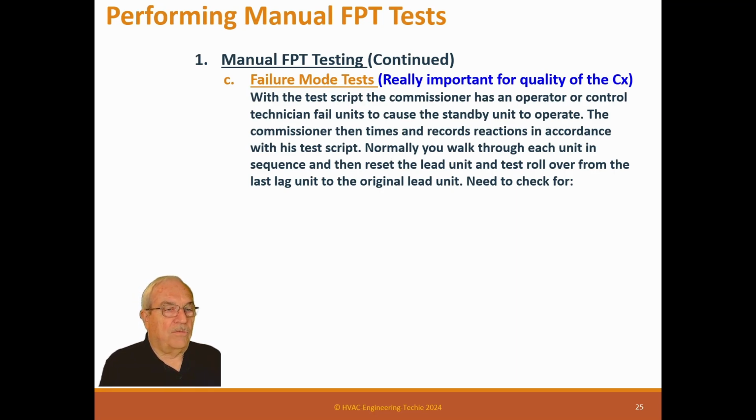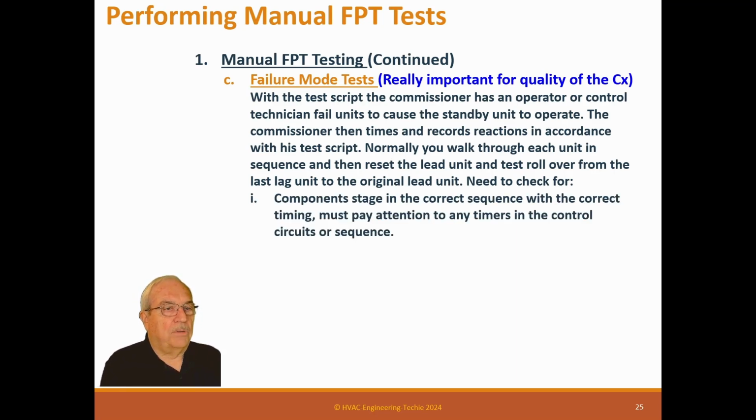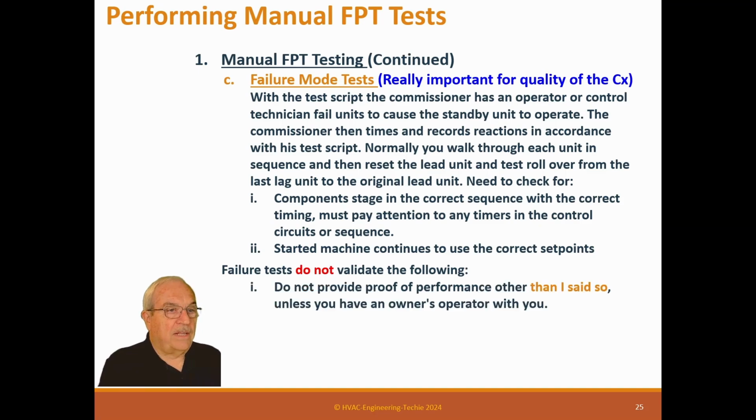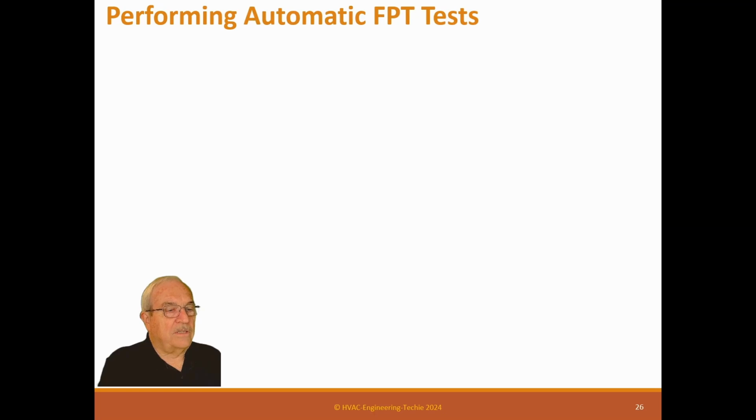Need to check for components staging in the correct sequence with the correct timing. Must pay attention to any timers in the control circuits or sequence. Started machine continues to use the correct set points. Failure tests do not provide proof of performance other than I said so, unless you have an owner's rep with you, like I just said.